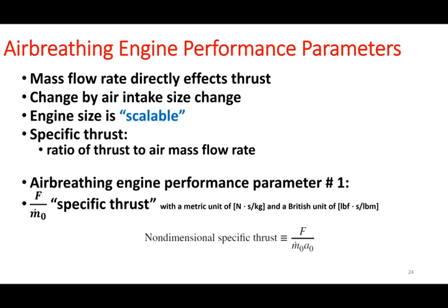Okay. The first thing you want to talk about is a specific thrust. You have to keep in mind that mass flow rate directly affects thrust. But the thing is, we can always change the mass flow rate by changing the air intake size, right? So the mass flow rate itself is not a real design parameter because it's a parameter you can always play with, even after designing your engine, with just a variable intake size.